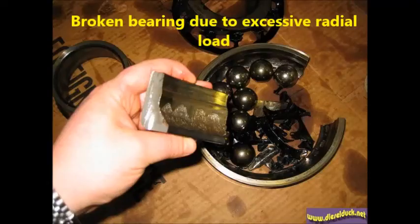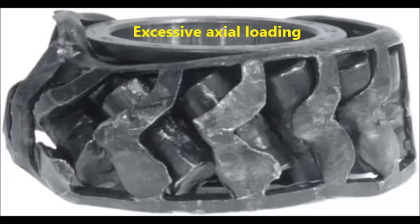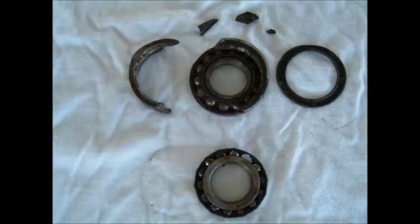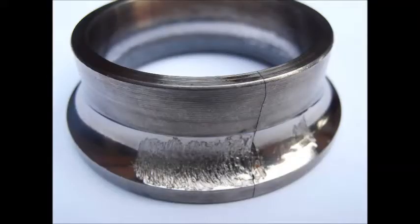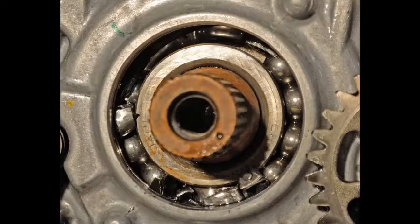Now, we would like to see why bearings fail. Even when bearings are used under ideal conditions, failure of bearings is caused by deterioration of material due to rolling fatigue. Generally, the service life of a bearing is expressed either as a period of time or as a total number of rotations before the occurrence of failure in the inner ring, outer ring, or the rolling element because of rolling fatigue due to repeated stress.